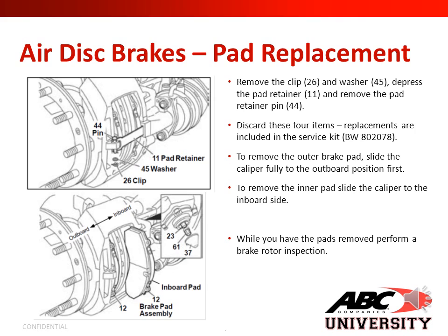BW802078. To remove the outer brake pad, slide the caliper fully to the outboard position first. To remove the inner pad, slide the caliper to the inboard side. While you have the pads removed, perform a brake rotor inspection.